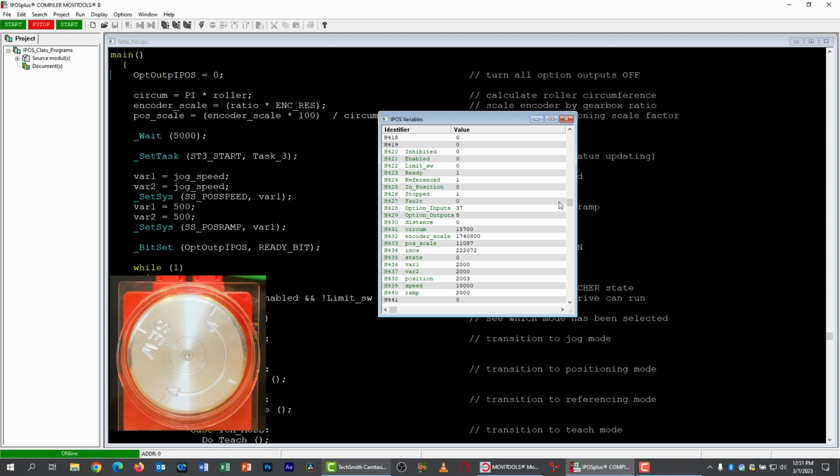It'll go back into positioning, and it'll just resume that positioning operation. If you leave DI12 on, that's exactly what happens. And you can see, there it goes, and it's positioned. So that is legal operation. That's just the way it works. I'll turn off DI12 now, and I will change back to row 2.